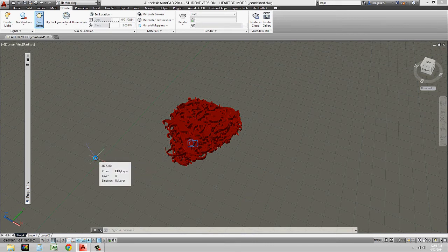So as opposed to doing that, I'm just going to continue with this lesson not doing that step. But just keep in mind that you'll have to do that through Autodesk 360, or you can use an earlier release and use a geographic location from that, or you can go to Google Earth. You can download Google Earth and specify a location in that program, then save that file from Google Earth as a KMZ file, and you can upload that from file into 2014.